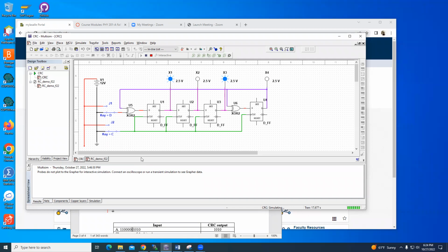The thing that is easy to get wrong is to grab an excluded NOR instead of an excluded OR, because it comes up alphabetically first. So that's the one thing to be careful about when building this: make sure you grab excluded ORs. And then